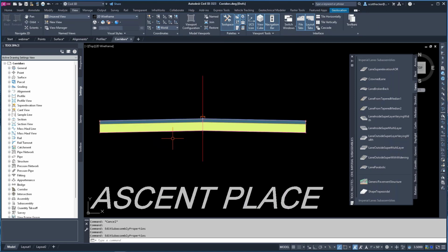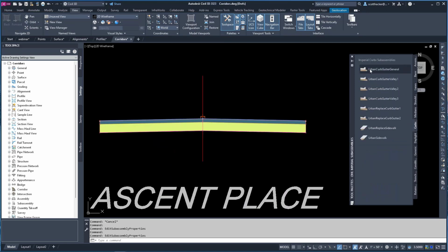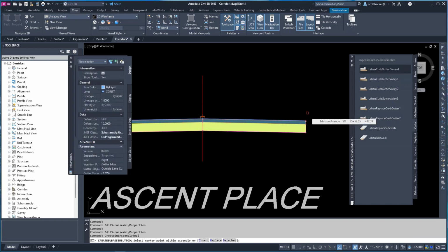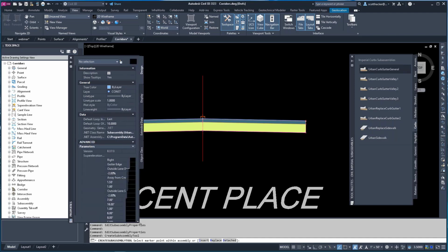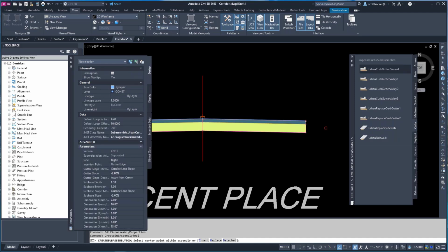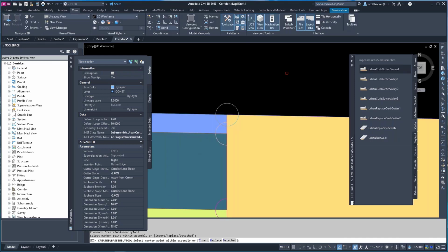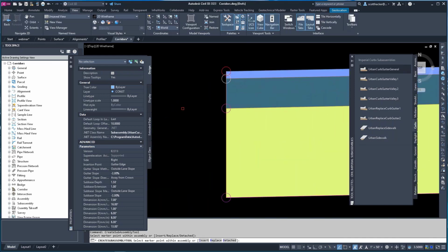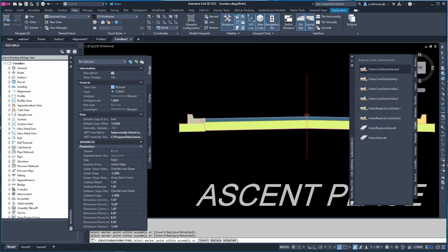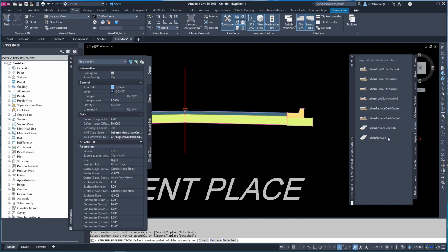Okay. Curb and gutter time. Urban curb and gutter general. As you can see, we've got several types. Okay. It's going to place it on the right-hand side. If we need to make any changes, we can do that here in our properties tool palette. Again, you're looking for a marker. These are now markers. And it will place it. We'll just say okay. It's always going to want, unless it prompts you otherwise, the top marker. There's our curb.